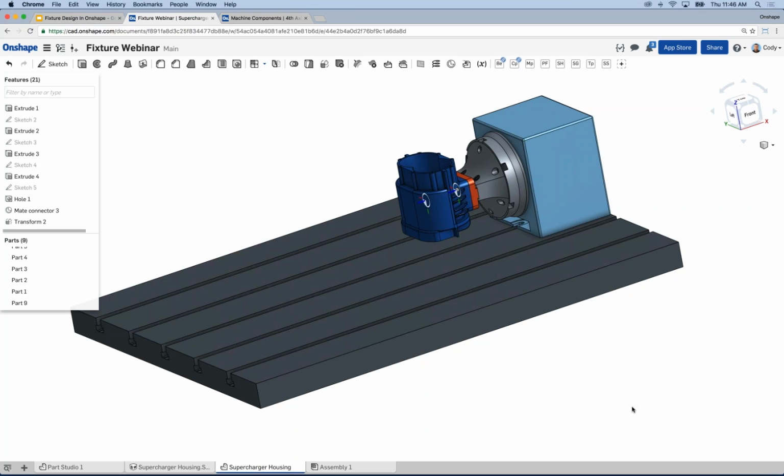Import the part, derive the part in, and then model it around it. The key thing, and probably one of the most important tips that I have for you today when you're doing this top-down design, is the transform with mate connectors. That is very similar to mates in Onshape assemblies, and it allows you to position parts in the part studio. So it's an important one, and I think for a lot of users, that's where it's easy to get hung up.